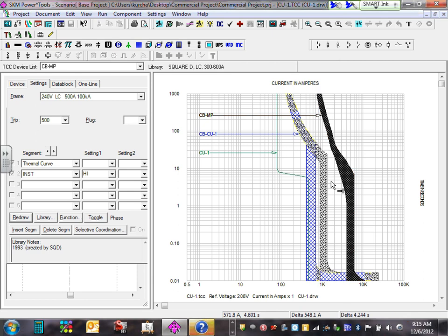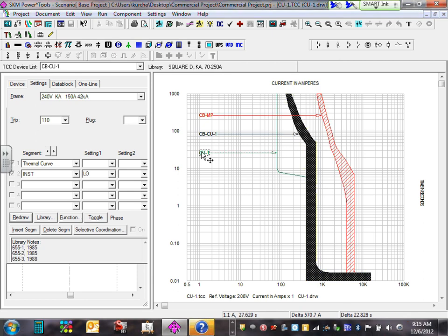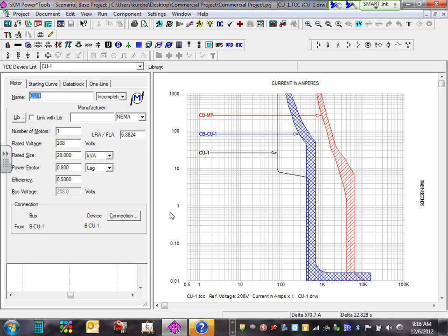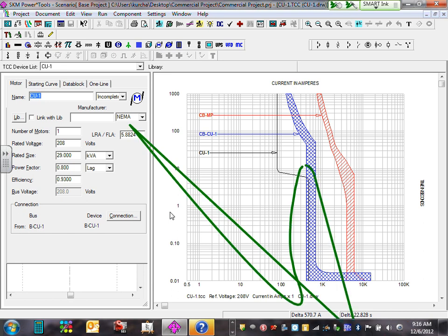And then, can you guys see, this is a good example of miscoordination. Now, look at this. Can you guys see the circuit breaker here is overlapping with the starting current? Everybody can see that? Did you guys get it? Darren, did you get that? No. Should we do it one more time? I put a different size, so it shifted it. But if you're looking at this, can you guys see the circuit breaker, this area here in particular? Every time you start your chiller, your circuit breaker will trip based on these settings. You will discover this day one, guys, when you start.